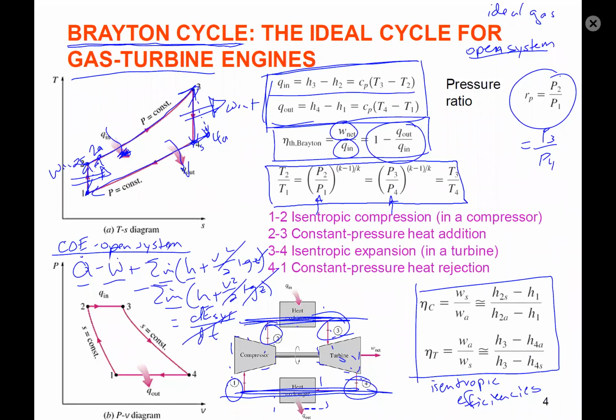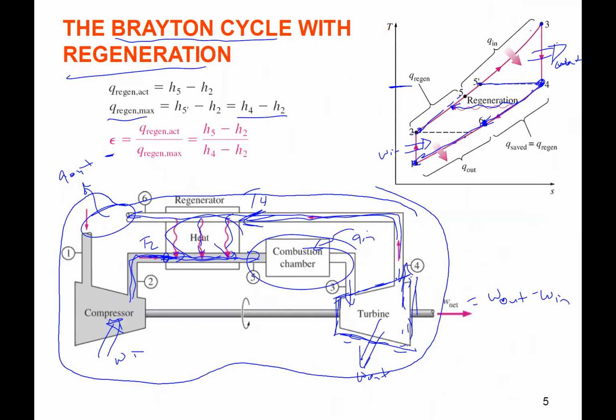So they all have compressor, heat exchanger, turbine, heat exchanger. So we still have the compressor, heat exchanger for heat in, turbine, and they're not showing it because they're just running out of space as it gets more and more components. They don't show it. You're exhausting to the atmosphere here with hot and bringing in fresh. So this is your heat exchanger. It's basically a heat exchanger. We're rejecting heat. So we have those 4 components for the Brayton cycle, right? So that's what defines the Brayton cycle. We've added a component, the regenerator. So it's still a Brayton cycle, but with regeneration. Okay.